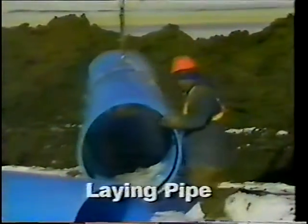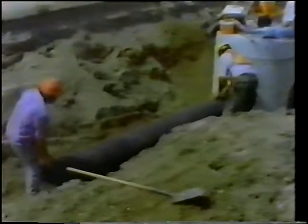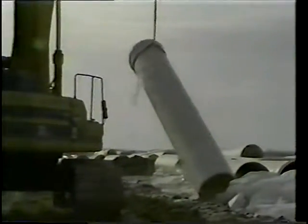Pipes should be checked for damage and cleaned of debris and then handled with care. Throwing or rolling the pipe into the trench can disturb the bedding and damage the pipe or its protective coating. The flexibility and impact resistance of plastic pipe reduces as the temperature lowers.